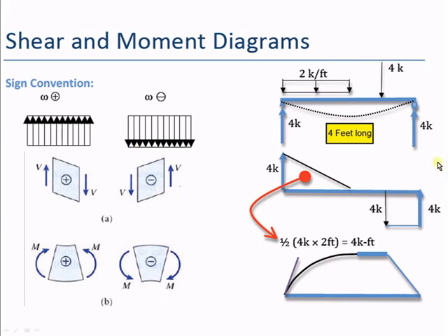Okay, and so here's just another example of doing a shear and moment diagram from our loading diagram. And this is to illustrate how you could do it graphically. Okay, so rather than creating a formula, why don't we just go ahead and use the fact that we're using integration and differentiation. These are all related as either integrals, integrating as we go down, or differentiating, taking derivatives as we go up of each of these formulas.